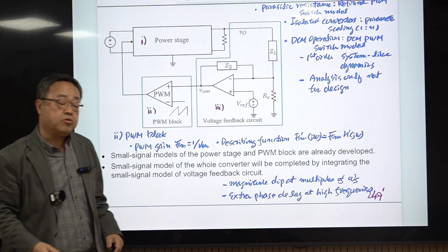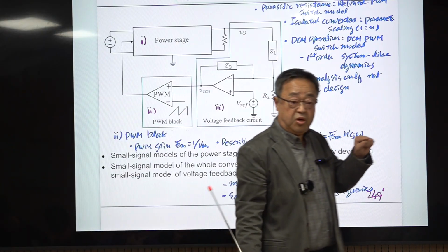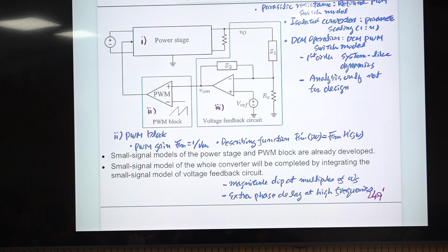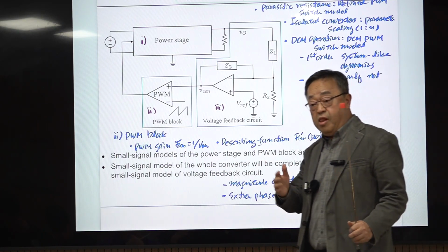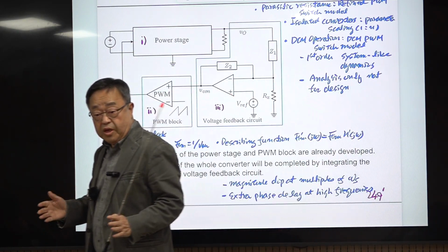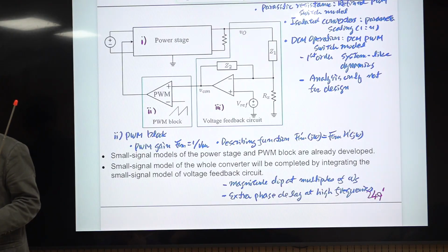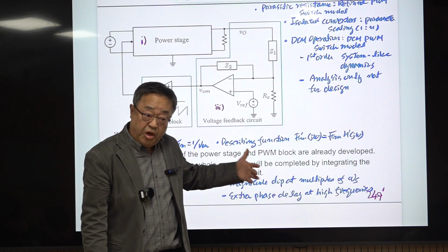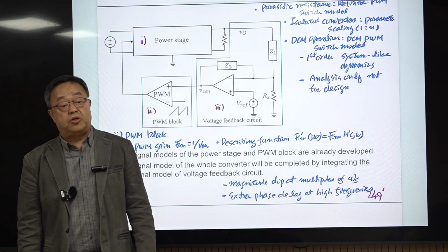At half the switching frequency, the delay becomes 180 degrees, and at the switching frequency, the delay becomes 360 degrees, with a duty ratio of 0.5. If the duty ratio is lower than that, the delay becomes smaller. So it's a function of the duty ratio, right? And this is apparent in the measurement and the computational method.